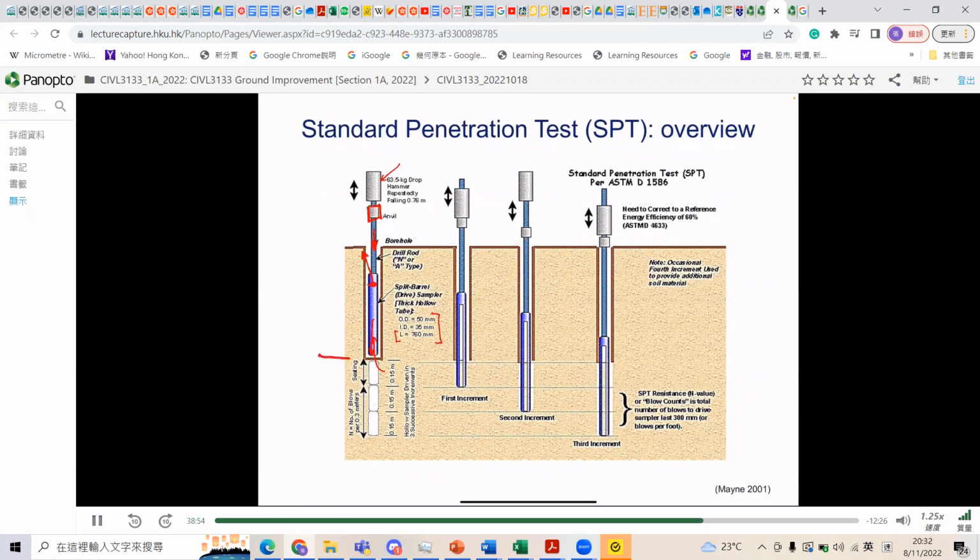And this is the elevation that we're initially interested in the ground. And you can see from the video that I showed you, we often bore to the elevation we're interested in using an auger. In the video, what happened was the hole was supported by the auger. So we used an auger, right, to drill into the ground to reach our target elevation. But in the video I showed you, we had something called a hollow auger.